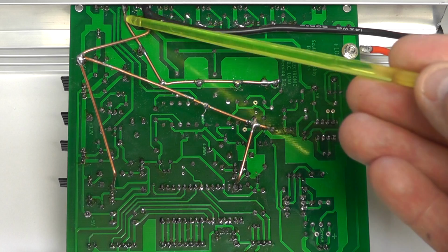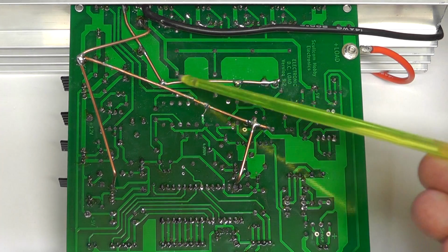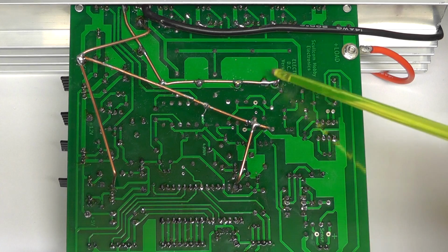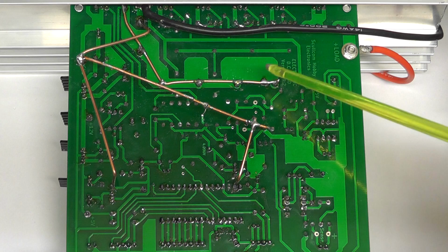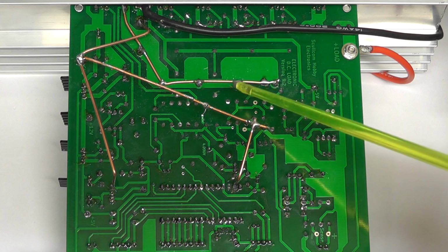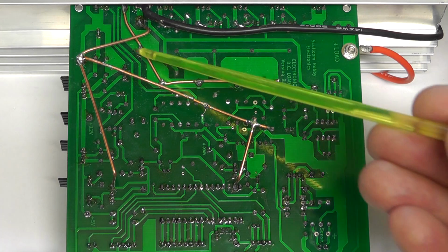So that's improving things as well, because although I did put wider tracks here on the printed circuit board on both sides, I still got some voltage drop on the print, and that did affect the overall performance. So by adding this additional copper track here, we're improving things there as well.